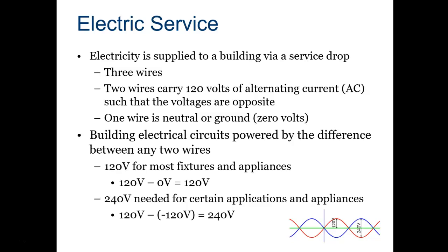The 2 positive wires, if you cross any of these 3 wires, neutral or ground, with either one of the 120s, it's going to arc and short. But if you cross the neutral and the ground, because they go back and connect to the same thing, they will not short. If you connect or touch the 2 120s together, they will arc also. In the lower right hand corner here you see this little diagram of the sine waves, the green being the neutral and the blue and the red being the two opposing 120 volt leads.